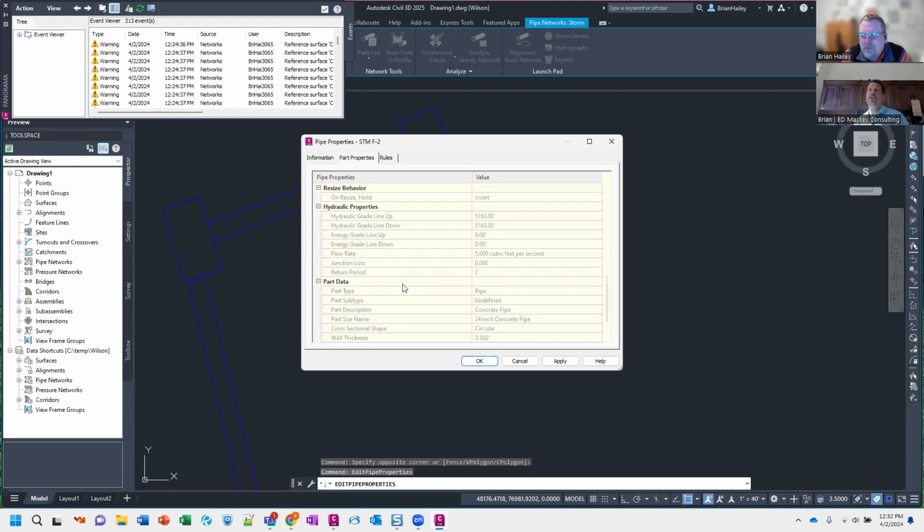And then see if it continues. Qt PDF is definitely missing data that Bluebeam or something else would give you. But it's my go-to to realize, is it an issue with my drawing or an issue with my PDF? Right. So you use it as a troubleshooting step. Yes, I don't ever use print to it, but hey, sometimes like, cool, I can print the Qt PDF just fine, so I know it's my drawing that's not corrupt. It's something about whatever PDF printer I'm using to try to get it out.